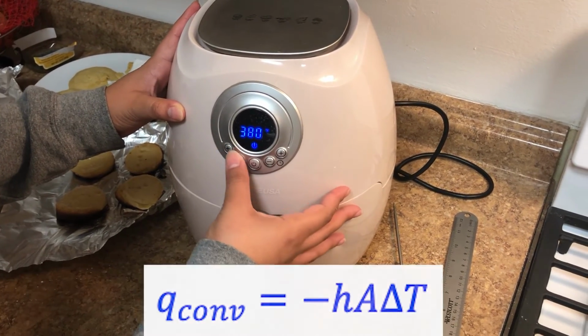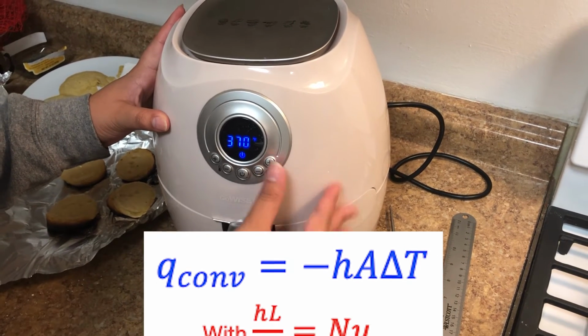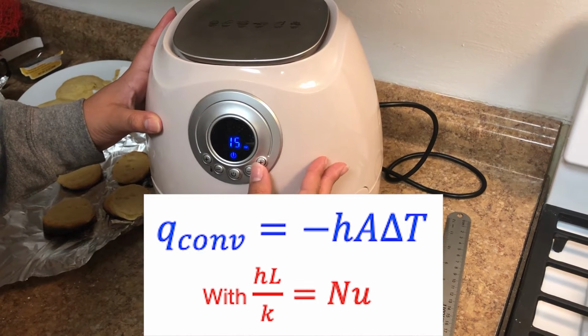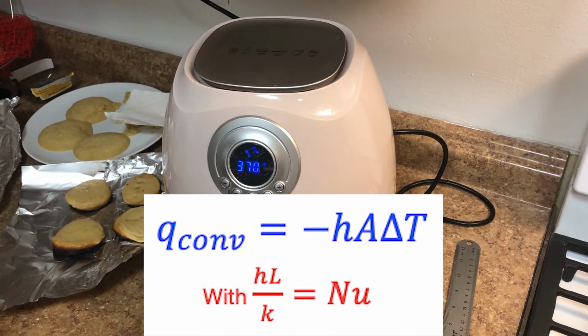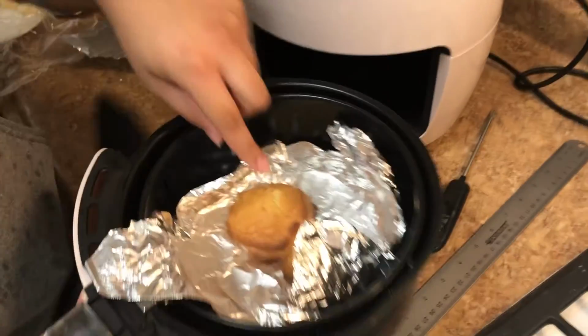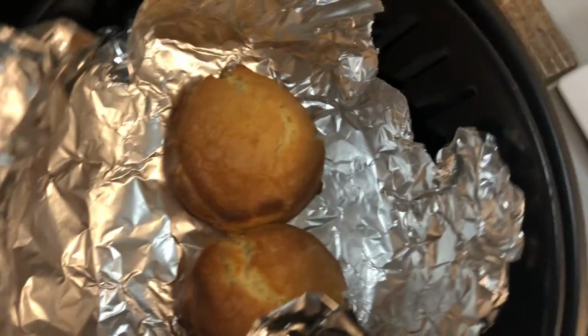Newton's law of cooling can be used to determine the heat flow from forced convection. The heat transfer coefficient can be determined based on the baking temperature or based on the Nusselt number. The area would be the surface area of the cookie after cooling, and the temperature change for the air fryer cookies can be based off the temperature difference in the center versus the top after baking.